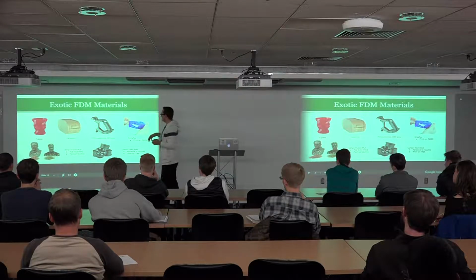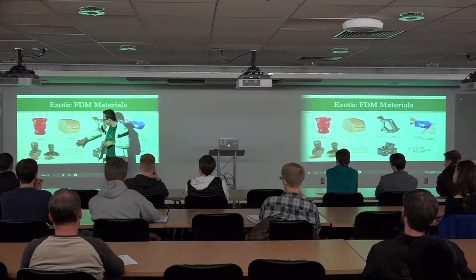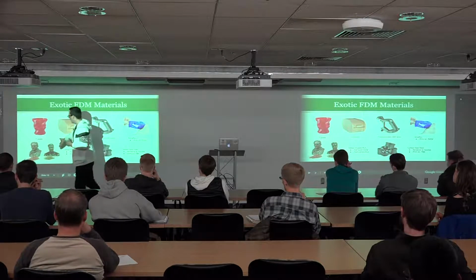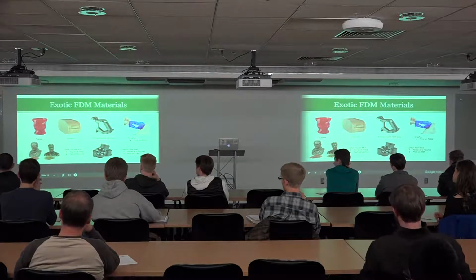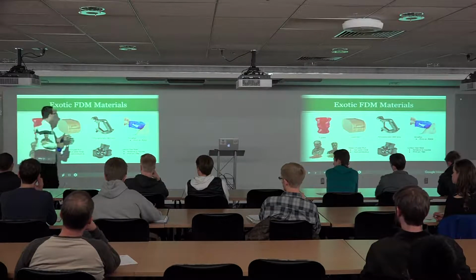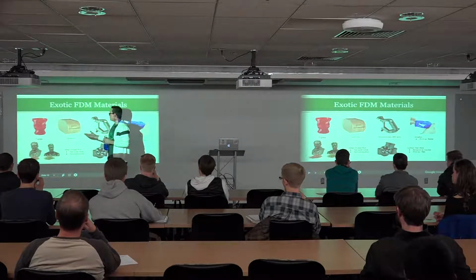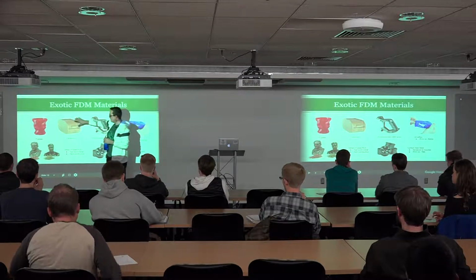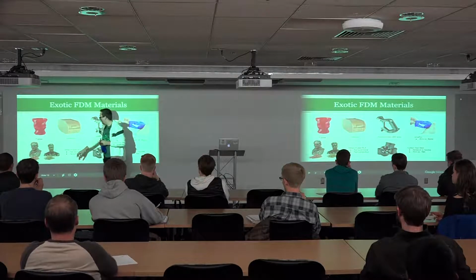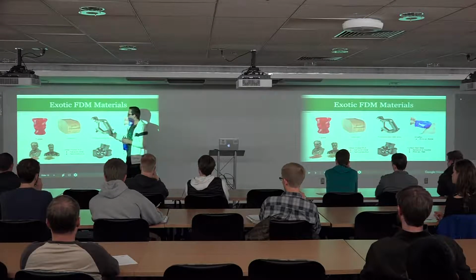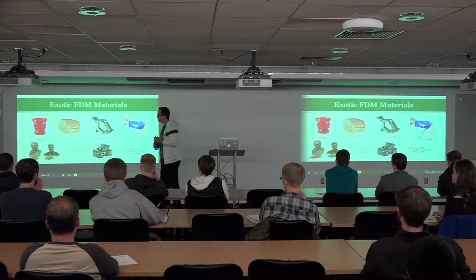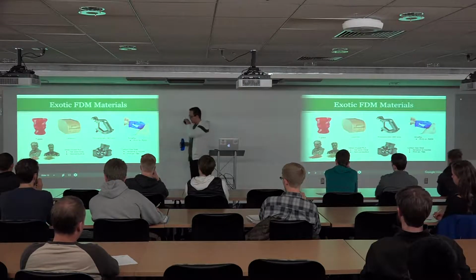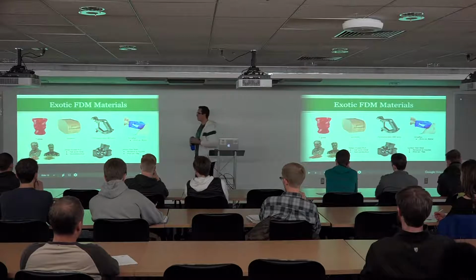Then laywood and some of these materials, the laywood and the metal-infused PLA, they are basically PLA with those materials added into them, and they extrude super easily like PLA and have some properties that could be useful. You can stain the wood. It's got actual sawdust in it. So you can stain it like wood. It looks like wood. The metal ones, you can polish them. You can rust them. We have some rusted iron PLA parts. So mainly for art projects, things like that.